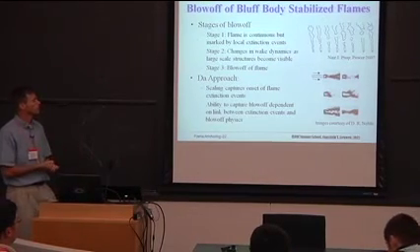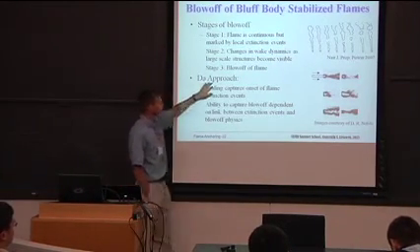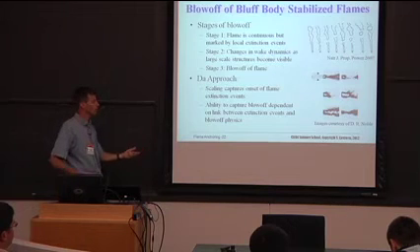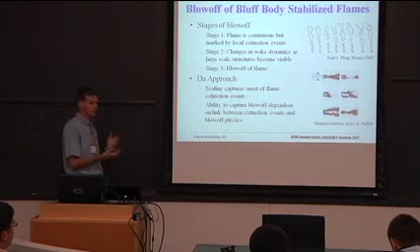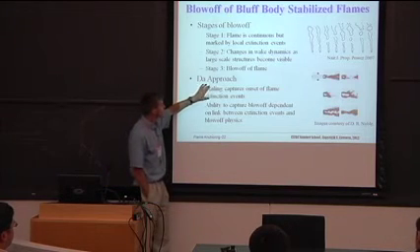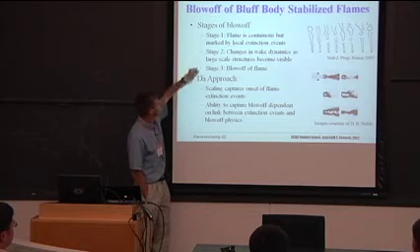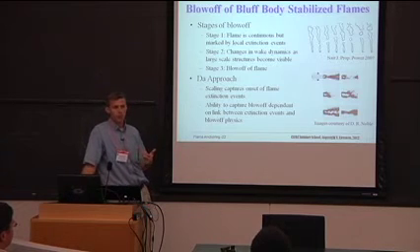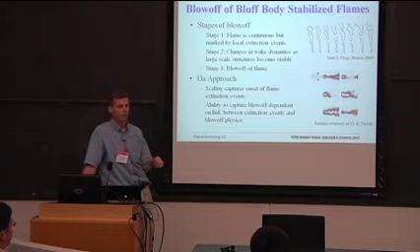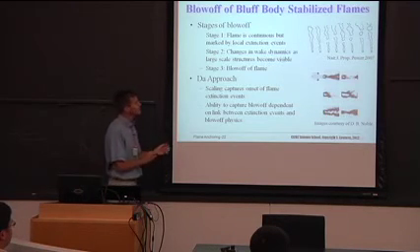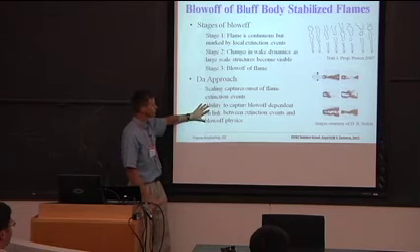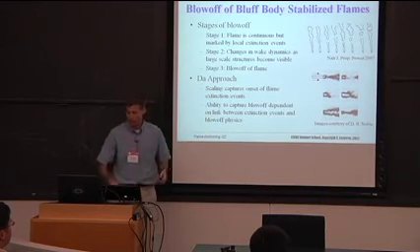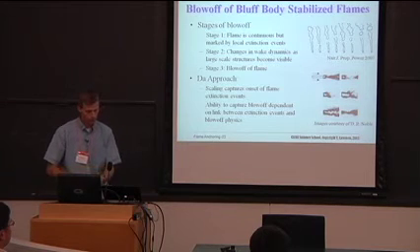So a very common approach to model blow-off is what I'll just call a Damköhler number approach, where you basically take a characteristic chemical time and characteristic flow time, or a characteristic flame stretch rate and extinction stretch rate, and you compare them. All right? Those are really not approaches for capturing blow-off. Those are approaches for capturing stage 1. What they're saying is, when am I going to start to get extinction on the flame? But as you can see, when you have product recirculation, extinction and blow-off are different things. So really what the community is doing to understand blow-off is trying to understand extinction. The reason they seem to work reasonably well is that the extinction event and the blow-off event are related, and they occur in certain regions.